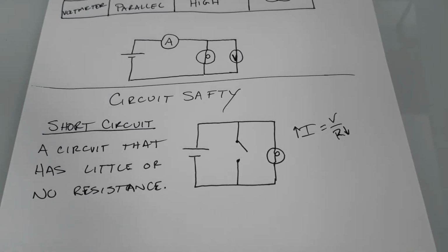And so oftentimes this would happen with space heaters. This is one of the most common ways that people will end up killing themselves, because they put several space heaters, the space heaters all kick on at once, and they draw so much current that they heat up one of the wires inside the wall of your house to the point where it catches on fire. And that fire will probably not be detected until the wall is completely engulfed in flames. And at that point, there's probably not much chance that you're going to be able to put it out, because the wall is going to be so hot from burning quietly on its own that even if you put water on it, the water will evaporate. And so you may not end up being able to put that fire out at all.